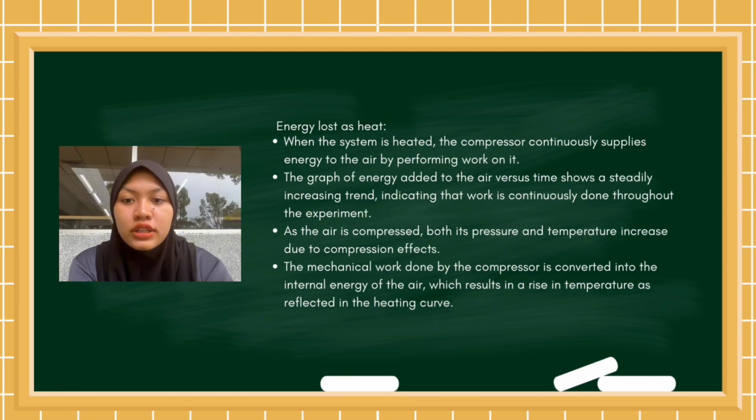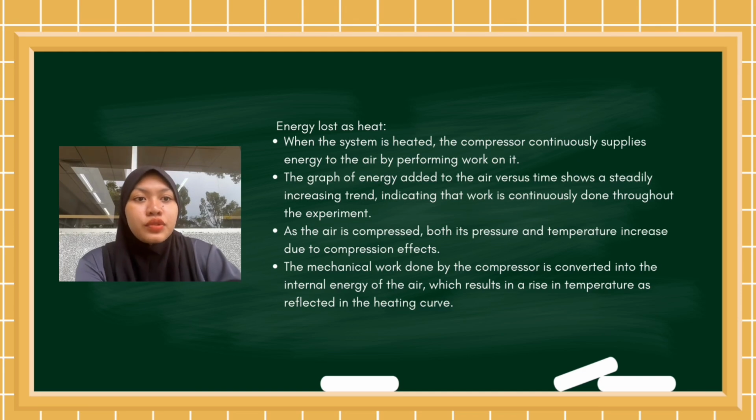The second discussion that we need to discuss is the energy that is being input to the system when the system is heated up. So the first is energy input to the system during heating. When the system is heated, the compressor continuously supplies energy to the air by performing work on it. The graph of energy added to the air versus time shows a steadily increasing trend, indicating that work is continuously done throughout the experiment. As the air is compressed, both its pressure and temperature increase due to compression effects. The mechanical work done by the compressor is converted into the internal energy of the air, which results in a rise in temperature as reflected in the heating curve.